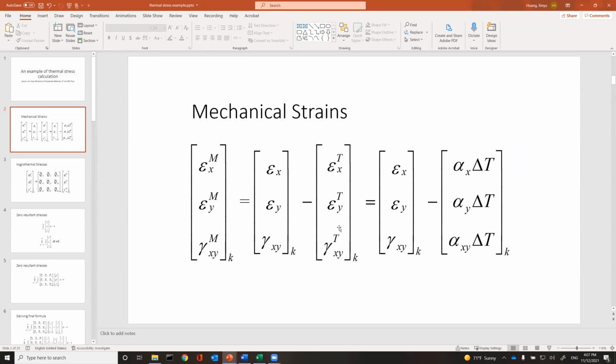Basically, the thermal strain is due to thermal expansion of the constituent materials, and the parameter that governs thermal expansion is delta T. Delta T is the change of temperature from a certain hypothetical stress-free temperature. You assume at a certain stage of manufacturing, let's say during curing, there is a state where the material is stress-free. Then the material gradually solidifies the matrices, and the differences are frozen in, and as such, you have thermal stress. So that term, alpha delta T, represents the material deformation due to change of temperature.